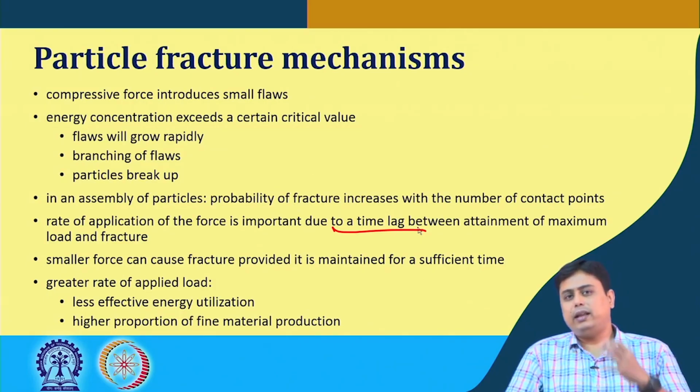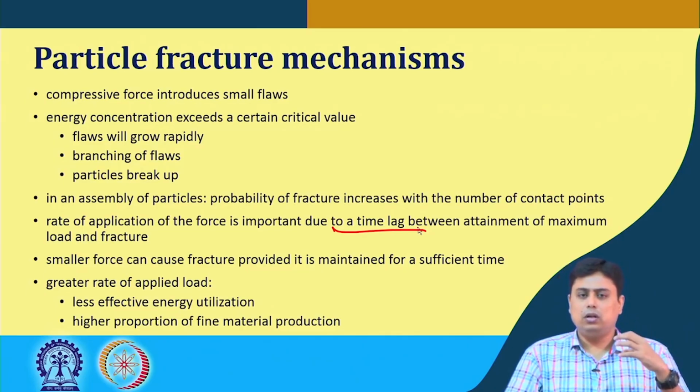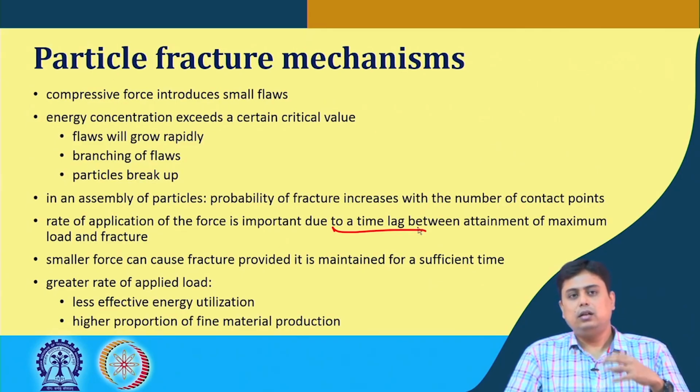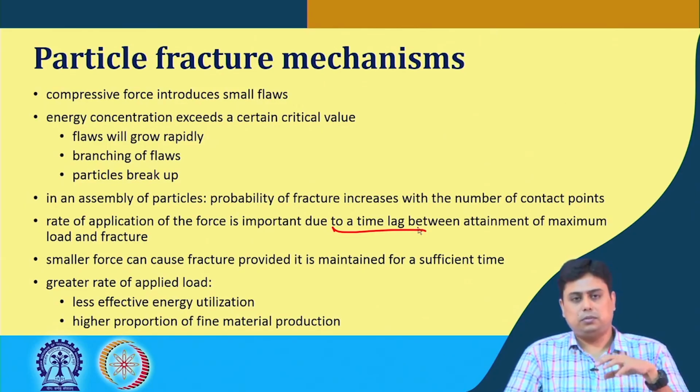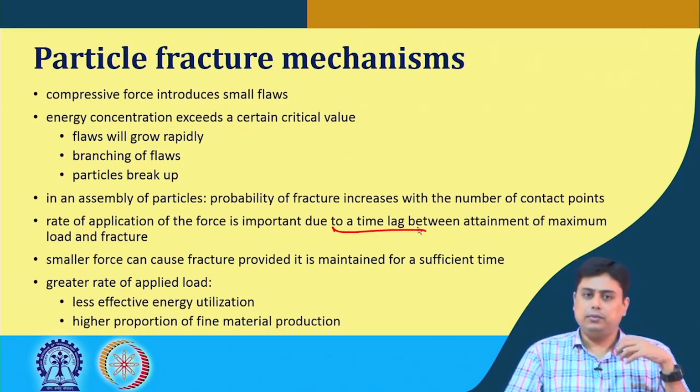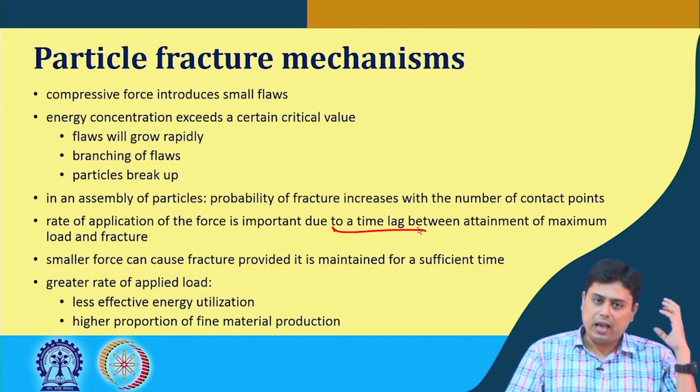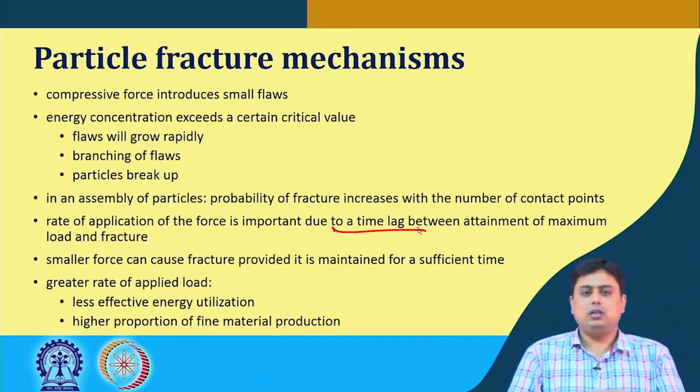Does that mean that if you have a sufficiently higher load, it cannot create a fracture? Yes, it can, but the greater the applied forces are, the less effective the process is in energy utilization. It becomes an inefficient process as you increase the applied load, contrary to the general belief that a very huge impact on solid rock is the way to do it.